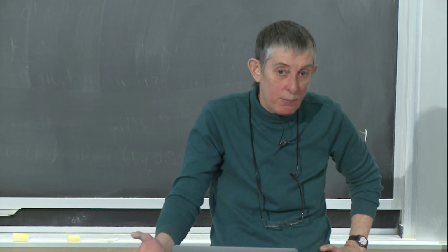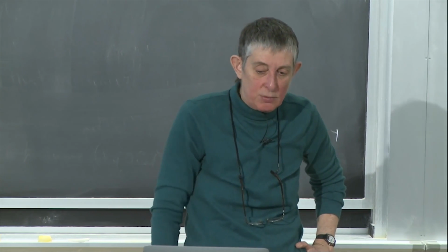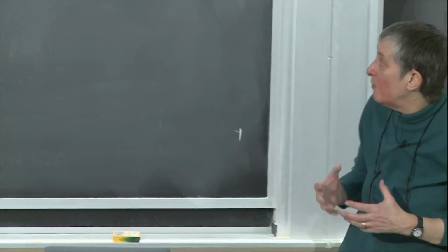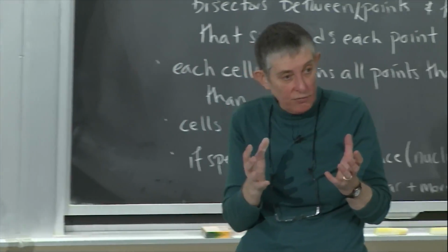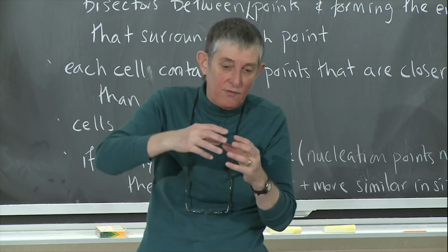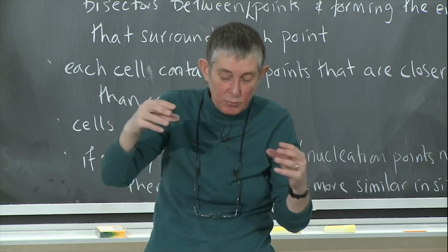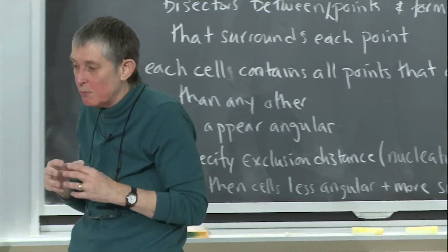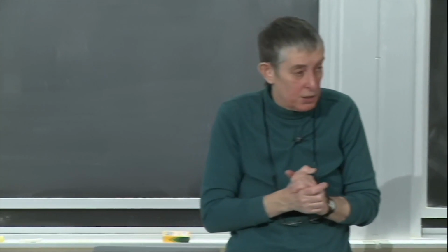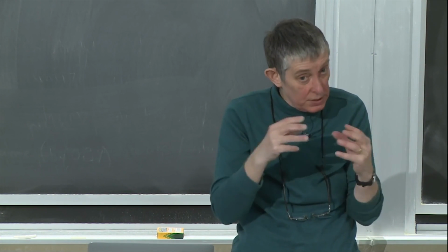And there's something called the fabric tensor, which characterizes the shape of the cells. And as you might imagine, the same as with the honeycomb, if you have equiaxed cells in the foams, you might expect you would get isotropic properties. If you have cells that are stretched out in some way, so you've got different principal directions or principal dimensions for them, then you've got an anisotropic material. Okay, and you can relate how much anisotropy to the shape of the cells.